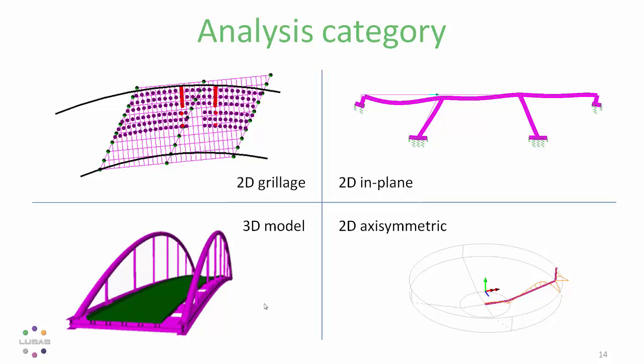But this is actually a massive deal, in fact, because what it means is that in version 16, as you choose that category up front, all the choices downstream are rationalized. So when you're looking at the line mesh attribute, you can't choose a 3D element if you're working in 2D, and you can't choose a 2D element if you're working in 3D.